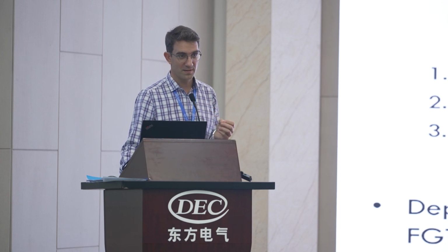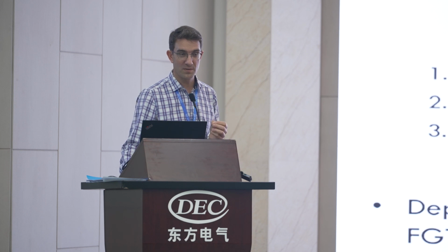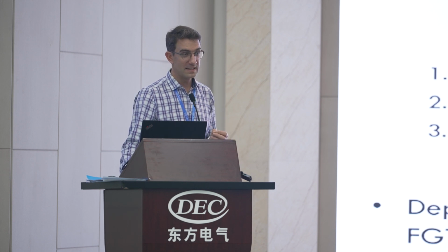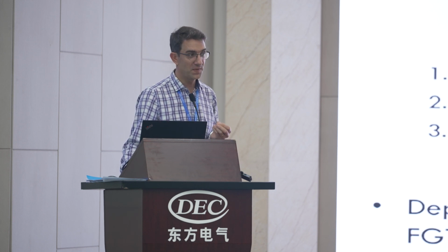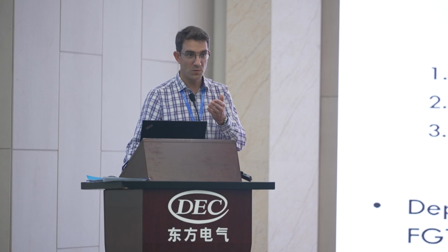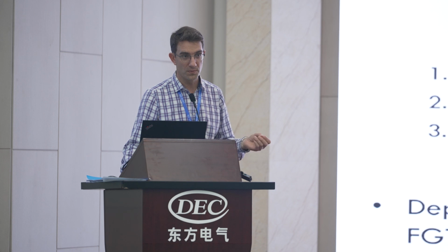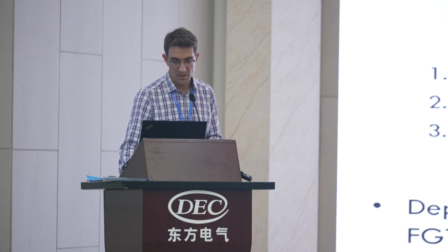and so this is to say that you really have to look at your flue gas treatment straight away when you're dealing with the CFB, because it can account for maybe 20% of your capex. And this is really also depending on which feedstock you're using. Professor Lee was speaking of biomass. For sure, with biomass there is no sulfur, so you have a lower capex for your flue gas treatment.